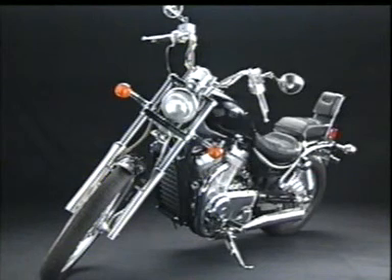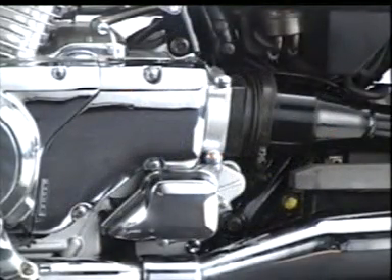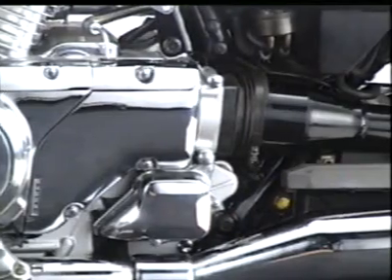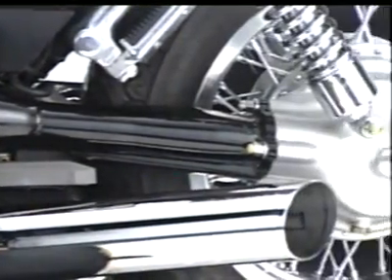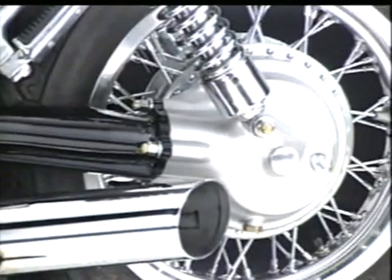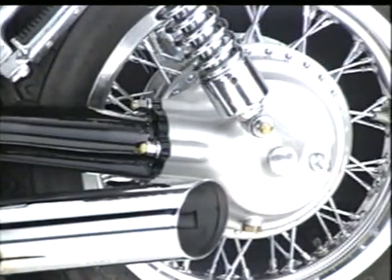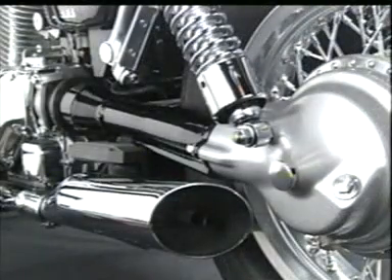The shock produced by changes in torque is absorbed by a damper attached on the drive shaft. When the damper on the engine side and the damper lifter on the drive wheel side are turned, the spring is compressed, acting as a shock absorber. Like the chain drive system, this is designed to boost riding comfort.